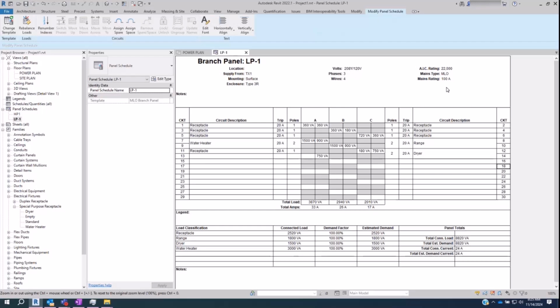You want to make sure your breaker is at least 15 amps, but in this case it'd probably be 20, because you normally put 20 amp breakers. I don't know if that's correct, but the amount actually accounted for the maximum amps on this panel would be that 11 amps. Is that correct?